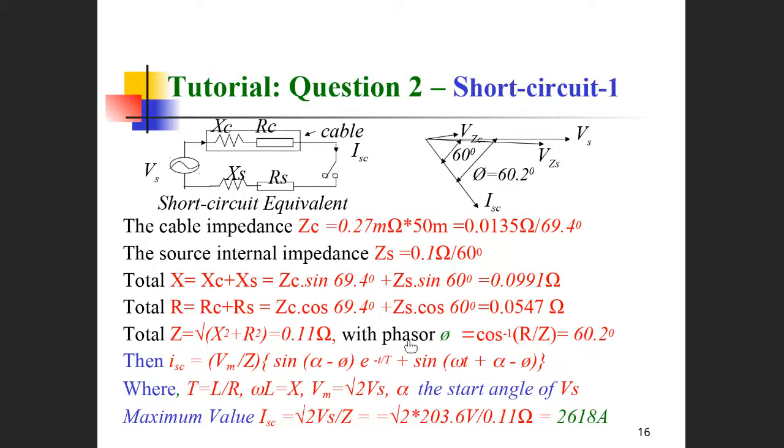With this information, one can quickly estimate the peak current at the moment of short circuit with the formulas we got in lectures. You will find that the peak current at the moment of short circuit is very large compared with the normal current, because of the small impedance of the cable and of the source itself. We have detailed procedures written in the tutorial examples, so you can take a look at them step by step yourselves after the tutorials.